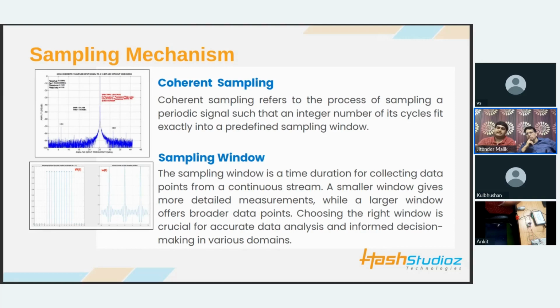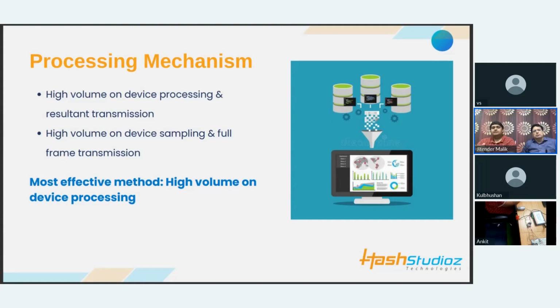Suppose you are measuring vibrations from a device, and the natural frequency of the device falls at, suppose, 2000 hertz, 2 kilohertz, right? In that case, if you're keeping a buffer of plus minus 20%, then somewhere around 5 kilohertz would be your exact Nyquist rate, and we can be sampling at that rate to produce the exact output.